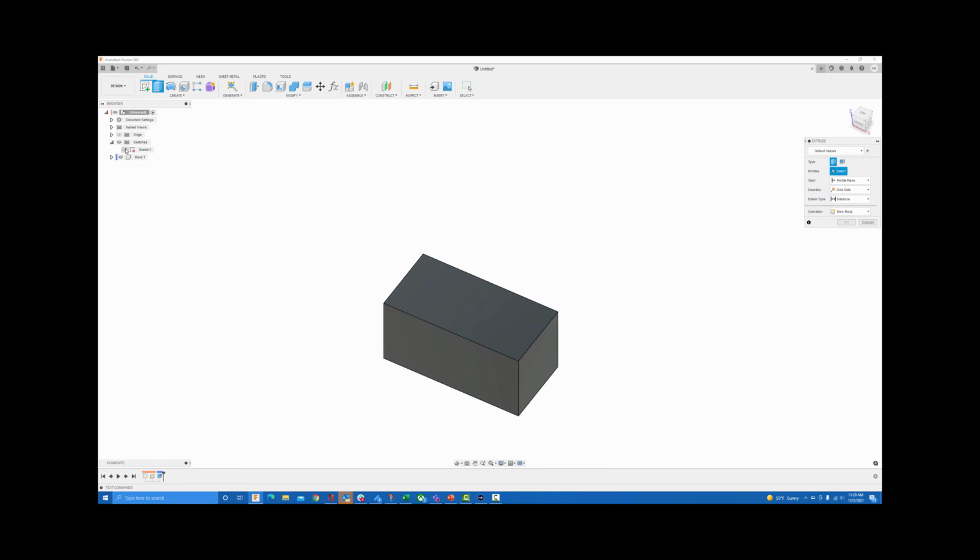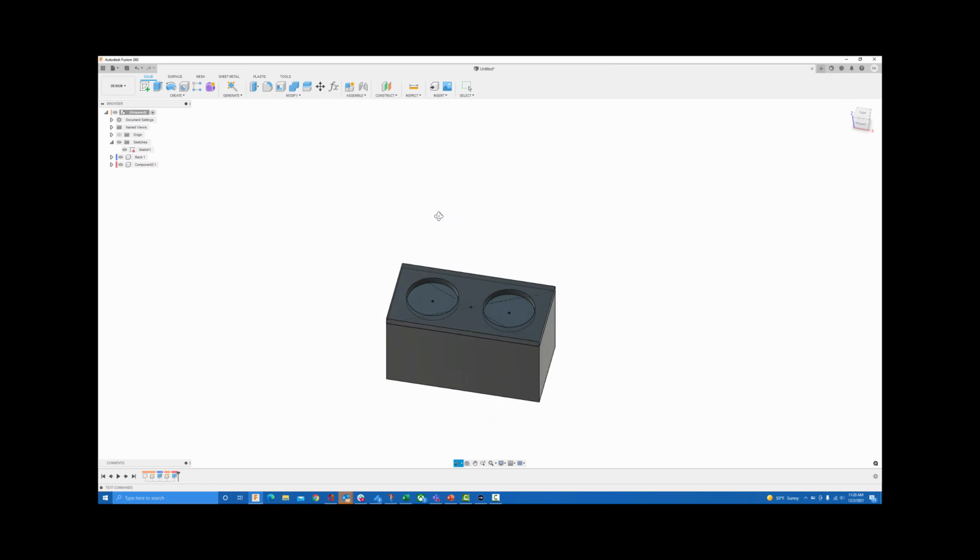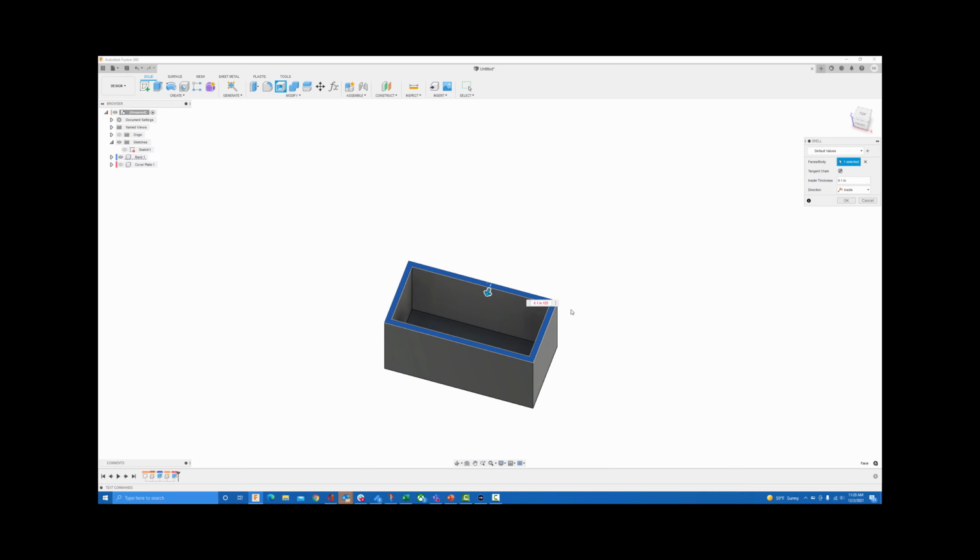And then we're going to extrude, we'll turn the sketch on and extrude that one, and we're going to do a new component, and we'll do something like a plate 0.125. So I have two components in there, and this one we'll just name cover plate. I like to keep things nice and clean and tidy, so I'll give them names. If I want to turn the cover off, I can turn it off there. I can turn off the sketch, and I can come in and say, let's just shell this out to be something like 0.125 as well.